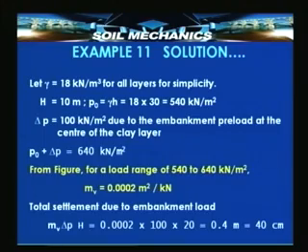Now, if this were not given, then either we can take the intensity of pressure at the center of the clay layer to be about the same as at the top surface, which is valid provided the preload is of a very large size and it is usually of a very large areal extent, or alternatively if it is of a very small areal extent, we have to use Boussinesq's theory and compute the intensity of pressure at any given depth due to a given intensity of pressure at the surface.